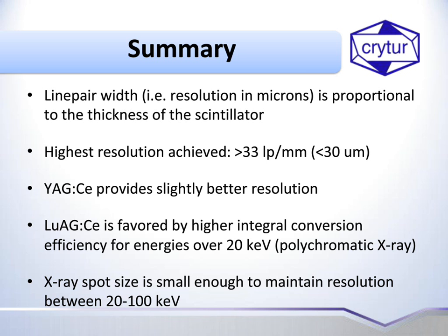May I add something? Yes, please. You can actually couple the scintillator just by pressing it on top of the fiber optics of the camera using some liquid, or you can use a fiber optic plate glued to a scintillator and then press it against the fiber optic input.